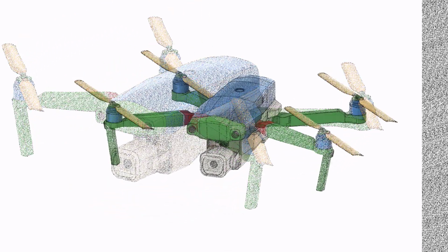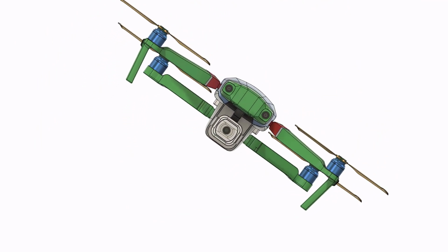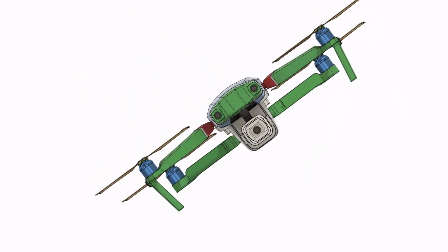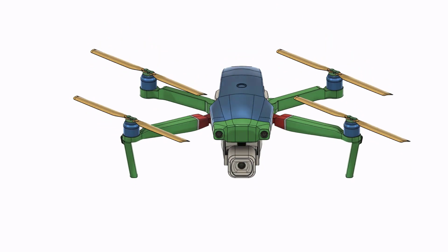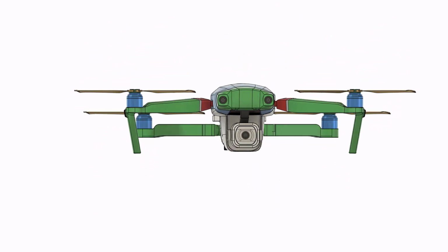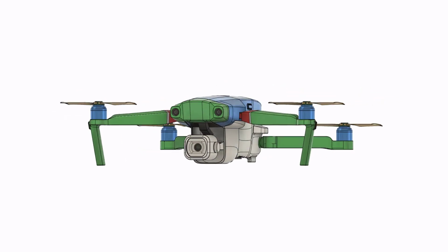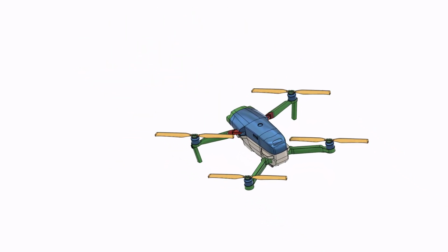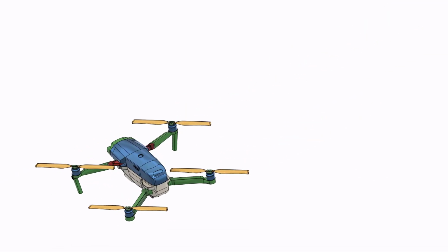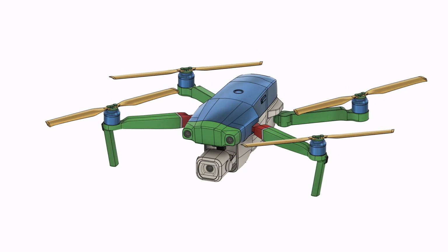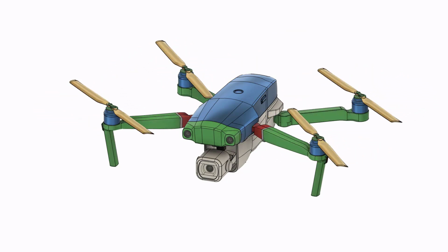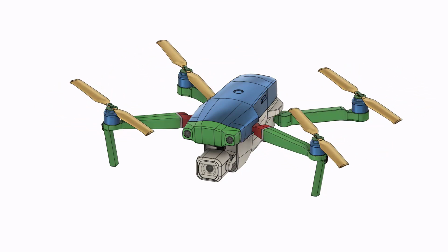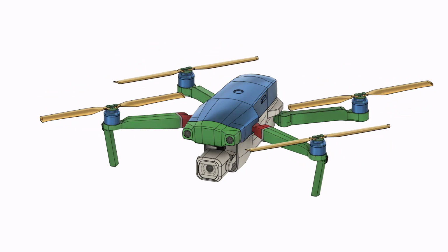This flexibility enables quadcopters and other multi-rotor drones to navigate through space with a wide range of maneuvers and effectively perform various tasks. These movements wouldn't be possible without the interaction of a number of forces. In future lessons, we'll discuss these forces in detail. However, 2 of these forces are thrust and torque. Each spinning propeller creates both thrust and torque. Thrust propels the quadcopter or any multi-rotor through the air and counteracts drag. To maintain a specific altitude, the thrust must balance the force of gravity, which pulls the flying machine downwards. In short, thrust allows the flying machine to maintain a specific altitude.